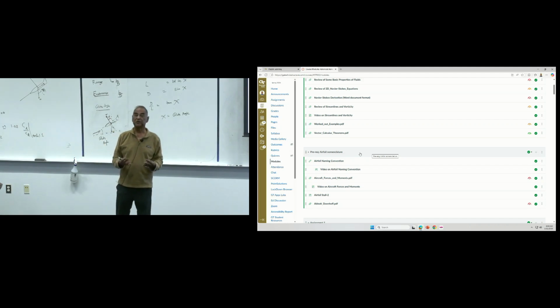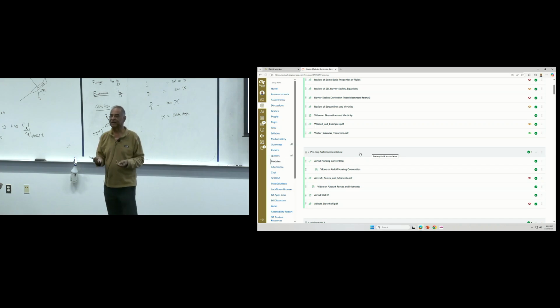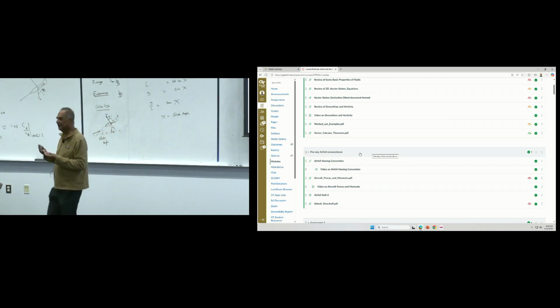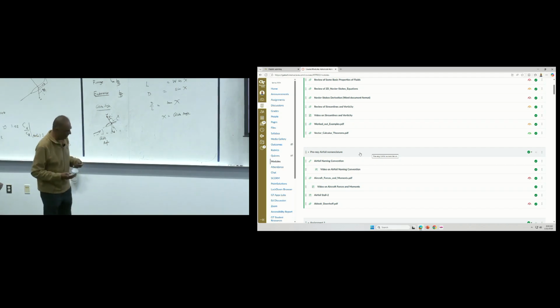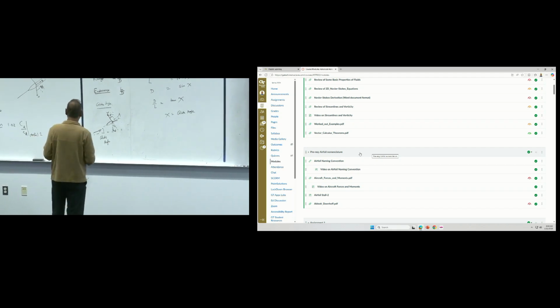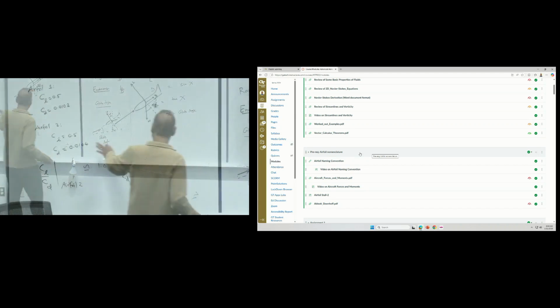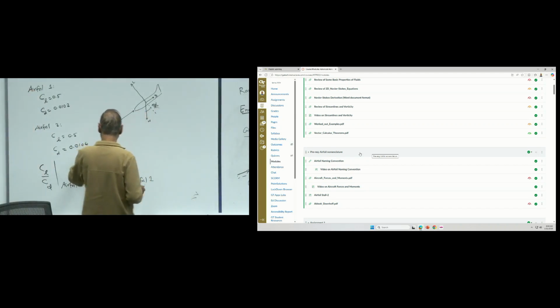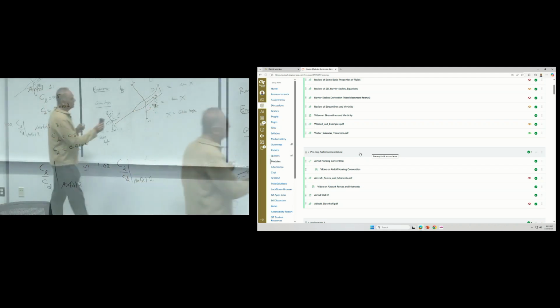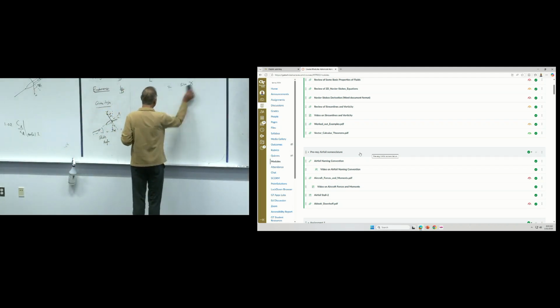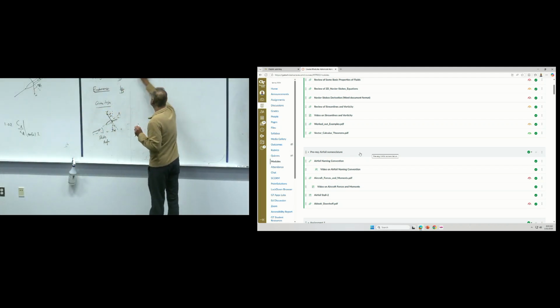So they will look at the drag count, because the lift is determined by the gross weight of the aircraft, payload, fuel you're going to carry, structural weight, and so forth. Of course, the structures people will be trying to make the structures as light as possible. So this is why I said you have to use the 4th significant digit. So that's very important.